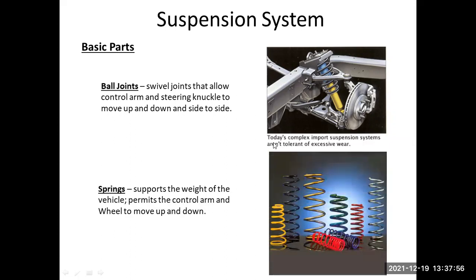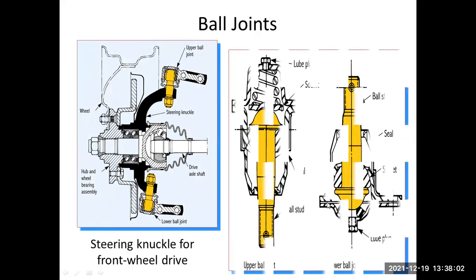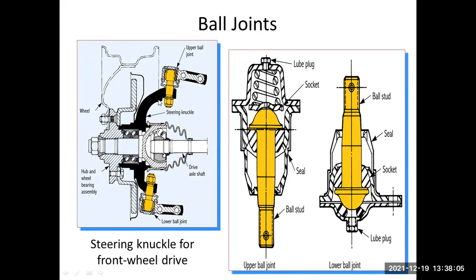The spring, obviously we require many types of spring. We'll be discussing the different types of springs. Then we have the ball joints. Here the ball joints are clearly shown in the case of a suspension system where there is no pivot pin. So this is a ball joint, and here is the axis inclination. We have discussed steering axis inclination earlier. It is the center line of this and this. This is one ball joint and this is the other ball joint. It is something like this, and it is going to move like this. This is where your suspension ball joints come into the picture.